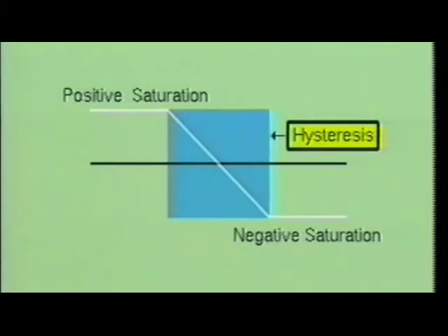This time is referred to as the hysteresis of the circuit, and the voltage between these two switching points is called the hysteresis voltage. Even though the positive feedback made the operational amplifier's output switch at a faster rate from one saturation point to the other, the transition time is much too slow for many applications. It can typically be several microseconds.